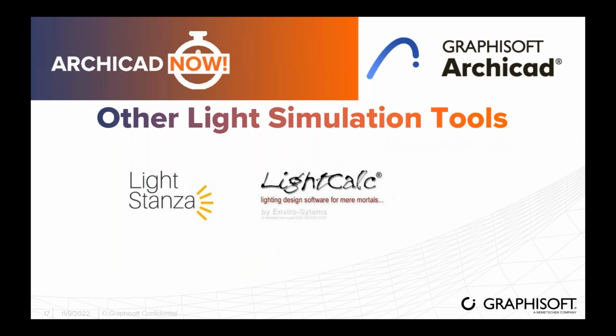All right, there are other simulation tools as I told earlier. We have Light Stanza, we have Light Calc. The Light Stanza tool can directly use the Archicad model. It's a web interface where you can just drag and drop the Archicad model, using which you can perform the light simulation there. And you also have Light Calc, which imports the IFC file, and you can work on the IFC file to perform the light simulation there.